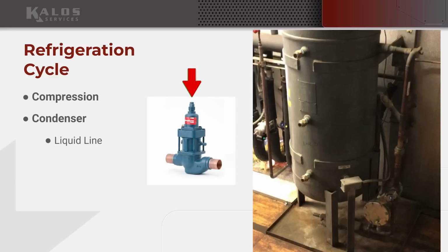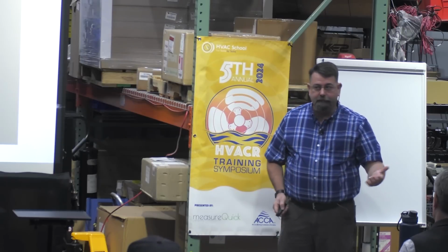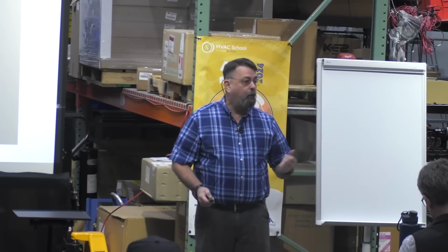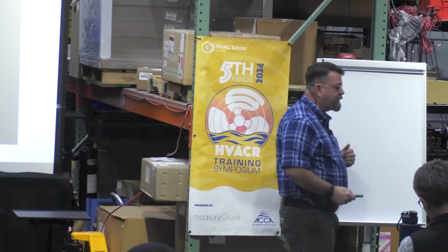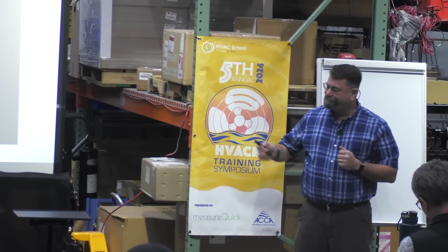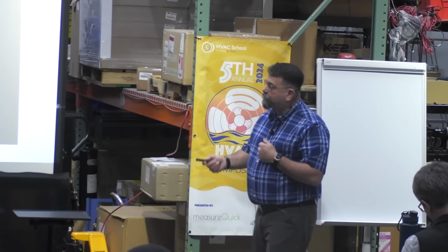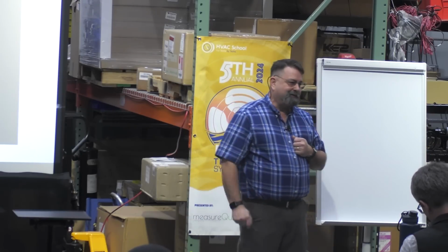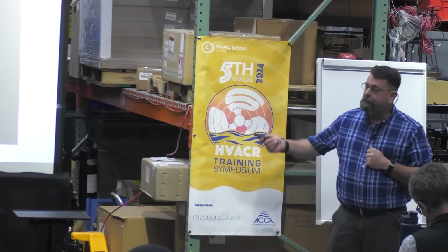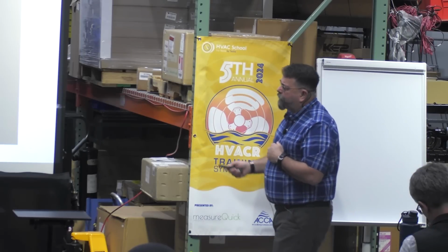Well, I'm going to have a valve on that liquid line that's going to cause that refrigerant to start filling up that condenser, making it even smaller because it's now got liquid in it, okay? We call that the hold back valve, right? So I'm going to have a hold back valve on this system in South Florida. We're probably not going to see that come into play very often, right? But as you start moving north, even I-10 right here in Florida, we will have nights where that comes into play. When we start going north of there, we hit the Great Lakes, we're running this guy 6-9 months out of the year, at night particularly, right? For sure. So it's a big piece there.